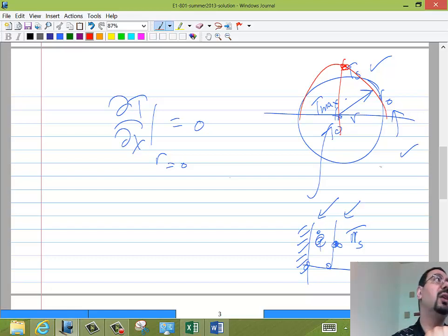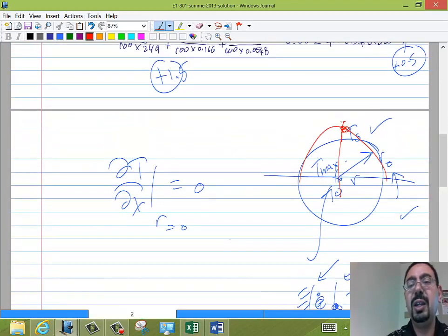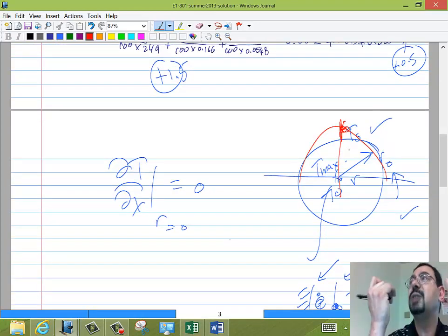Whether he thinks it's correct because this is the maximum, or because of the symmetry, or whether he could also think that at the center line, the heat going to the right and to the left is exactly the same. It's really as if there is no flux going outside the center line because of the symmetry. It's not going to the right or to the left. Anyway, it's because of the symmetry: the partial T, partial X is 0 at the center line.